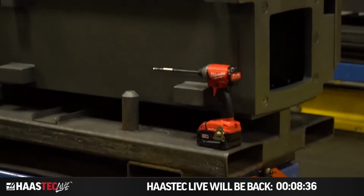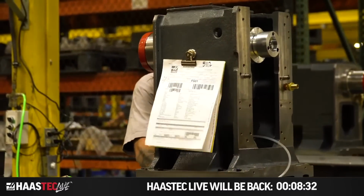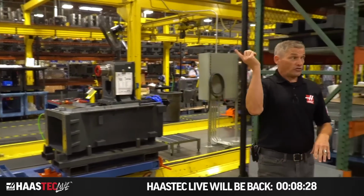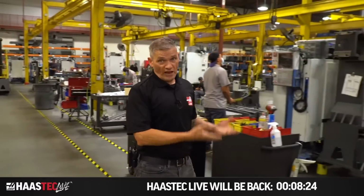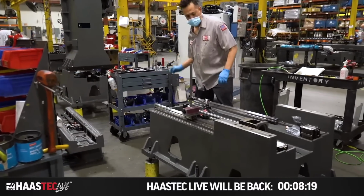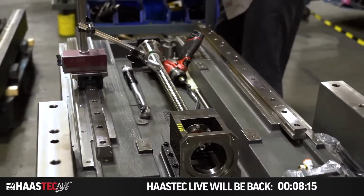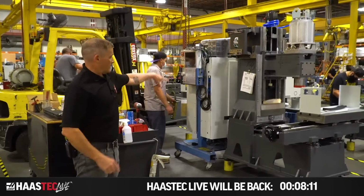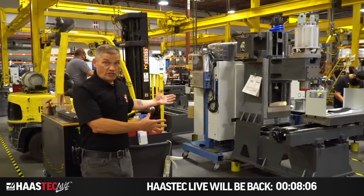This is our highest volume column assembly that we make here. You can see that this is kitted, ready to go, so that once it's assembled here, it's taken over to this side. This is where we do the entire stacked axis method we were talking about earlier. We place the base on the ground, add the linear guides and ball screws, install the saddle and table, and then we take that column assembly that we built over here, lift it with a crane, drop it onto the top of this guy here, and you essentially have the bare bones of the machine.